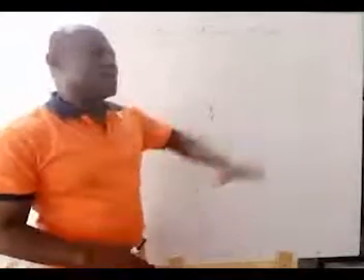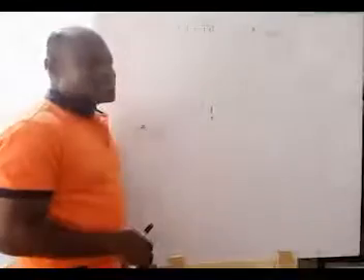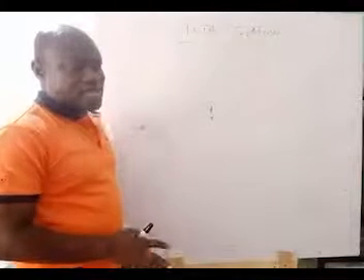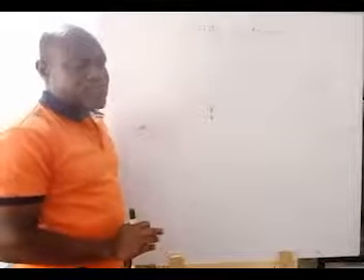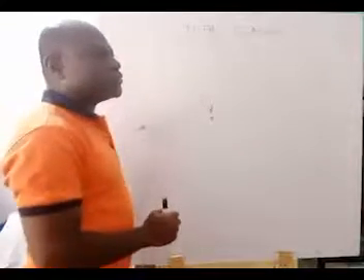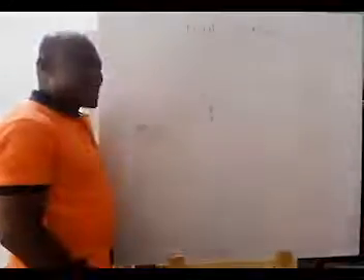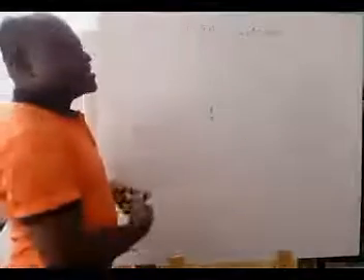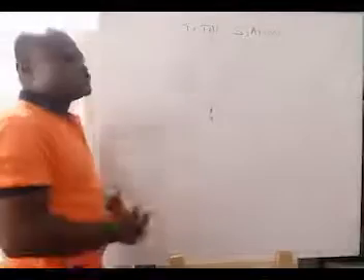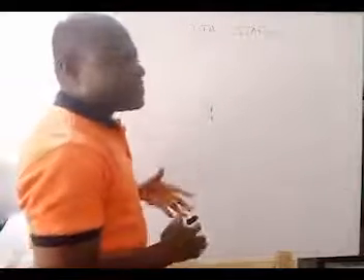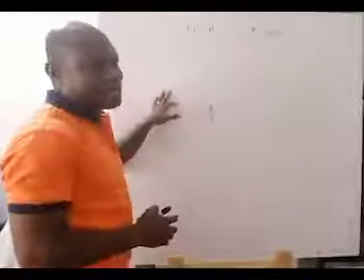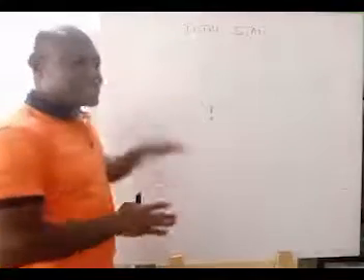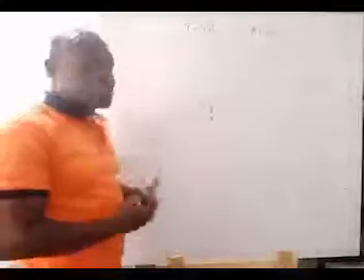If you want a level concrete floor, the total station can help you to set it out like a level. It can also help you to set out drains. So with that, you don't even need a tape. All you need is to input the coordinates of start and finish, and use the line function. Then you can set out the drain invert at a certain slope, like the design slope.